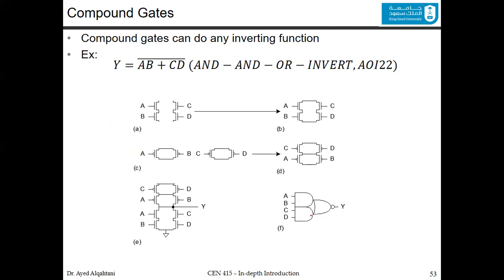To show this at the logic level, we don't have any lines here, to show that this is a whole unit. This is a compound gate. Also note that you have a bubble here indicating the bar. You have the OR indicating this OR, and you have two ANDs indicating the two ANDs. And from here, you can see also the name: AND-OR-inverter 2 and 2.